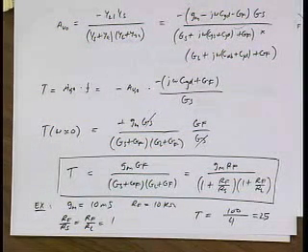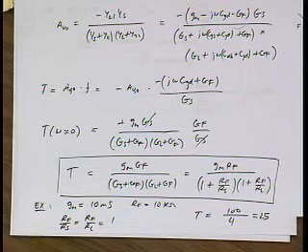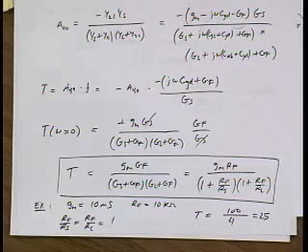So the reason I paused to look at that is actually you'll see this when you run simulations, right? If you have an amplifier and you look at step response, what's the first thing you see? You actually see the amplifier at first going in the wrong direction, right? I'll give you an analogy. Let's say you have a cruise control system. You're driving your car, and you set your speed to 50 miles an hour, and you press the button, and let's say you're going 70. So instead of slowing down, the first thing the car does is it speeds up. It speeds up to 90 miles an hour, and then it slows you down to 50.